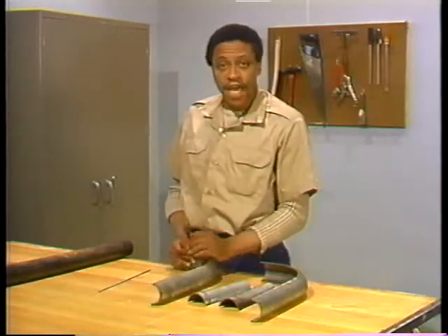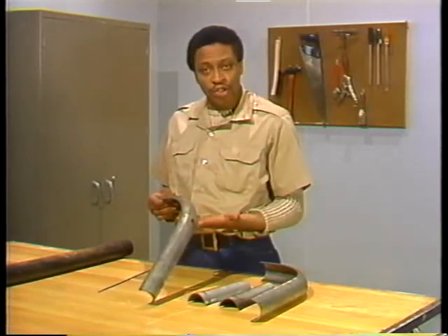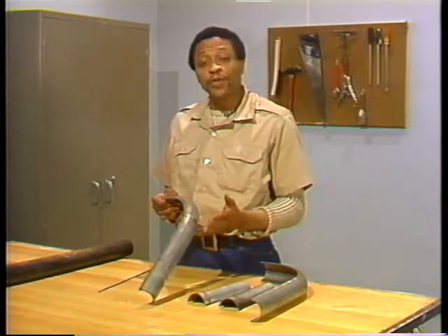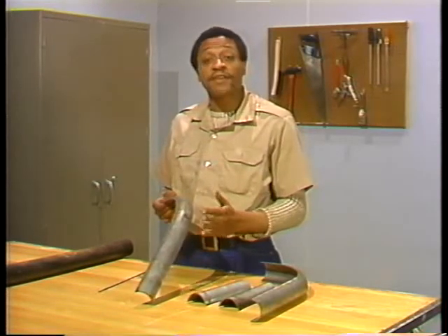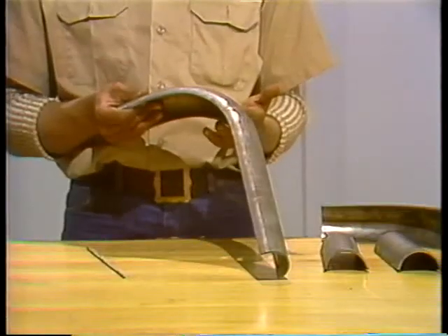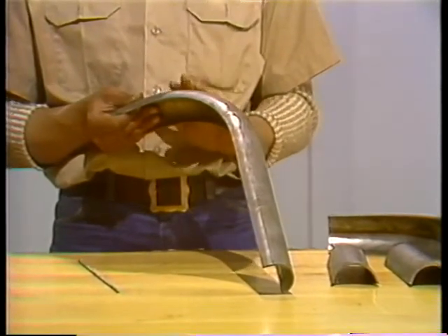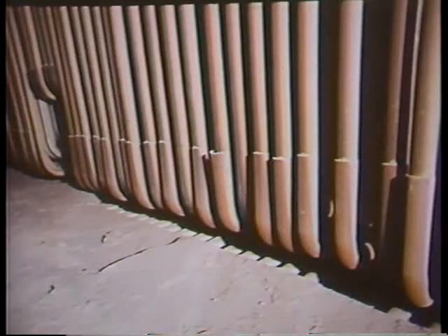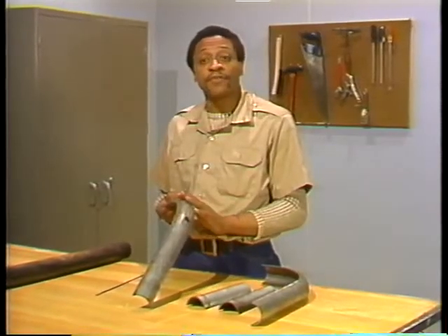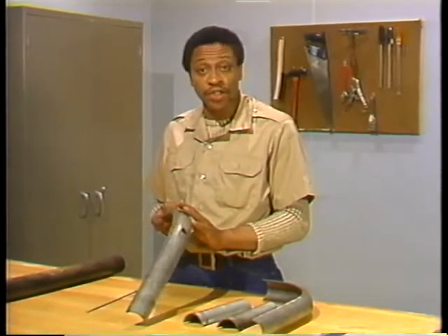If tubes are thinned only from erosion on the outside of the tubes, a tube shield is sometimes used instead of a clad patch. A tube shield is a metal plate, usually made of stainless steel, that is bent to fit over a tube. It is put on the side that is subject to thinning and then tack welded or clamped in place. The tube shield is effective in preventing continuing thinning from erosion on the outside of the tube.